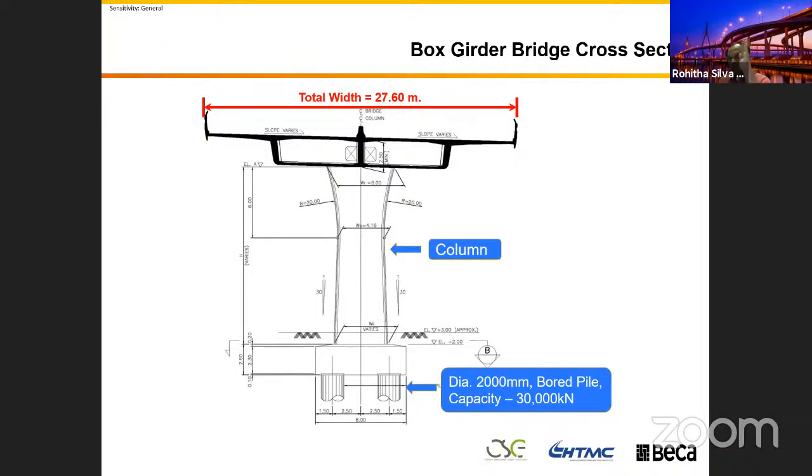When you make your bridge substructure or the column flexible, then you can let your structure deflect more. When there are creep shrinkage forces, because we build this bridge like a monolithic structure, you will see this detail later, all the forces applied on the bridge are not going to translate into the structure, because part of that will translate into deformation.